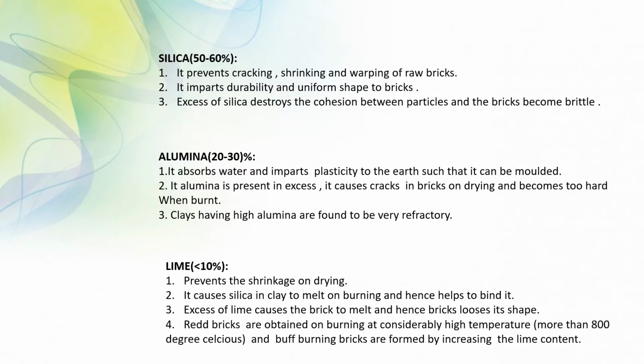And next I will briefly discuss the good composition of bricks. Silica, 50 to 60%. Number 1, it prevents cracking, shrinking and warping of raw bricks. Number 2, it imparts durability and uniform shape to bricks. Next, excess of silica destroys the cohesion between particles and the brick becomes brittle.